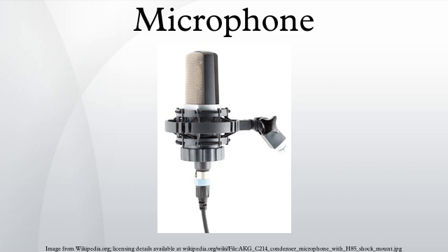Condenser microphones are also available with two diaphragms that can be electrically connected to provide a range of polar patterns, such as cardioid, omnidirectional, and figure-8. It is also possible to vary the pattern continuously with some microphones, for example the Audio-Technica AT4050 or CAD M179. A valve microphone is a condenser microphone that uses a vacuum tube amplifier. They remain popular with enthusiasts of tube sound.